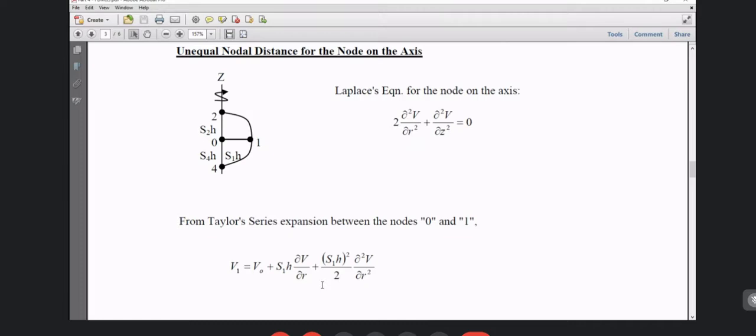And once again, for recapitulation, the axis of symmetry represents the rotational symmetry of 360 degree, so any flux line will be only on the right hand side on this diagram, because if it crosses the axis of symmetry, then the rotational symmetry will be lost. So on the axis of symmetry, the flux line is tangential to the z-axis.